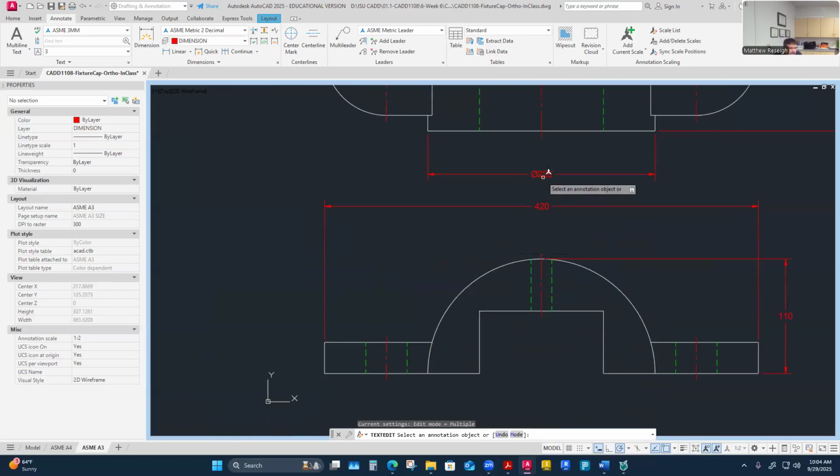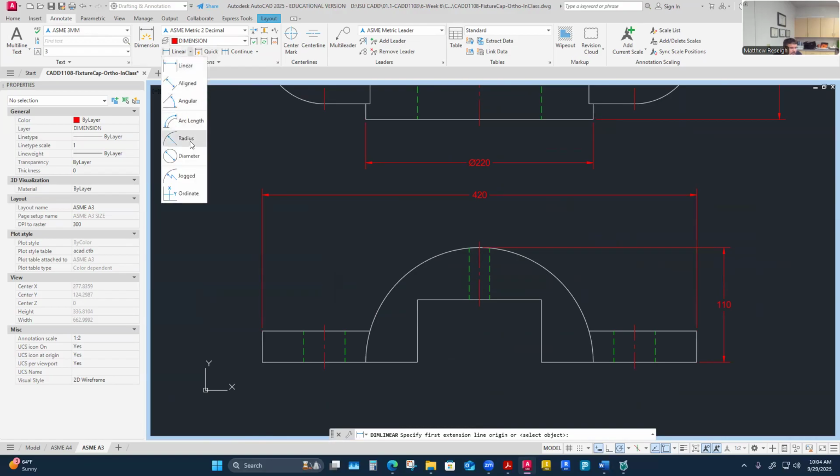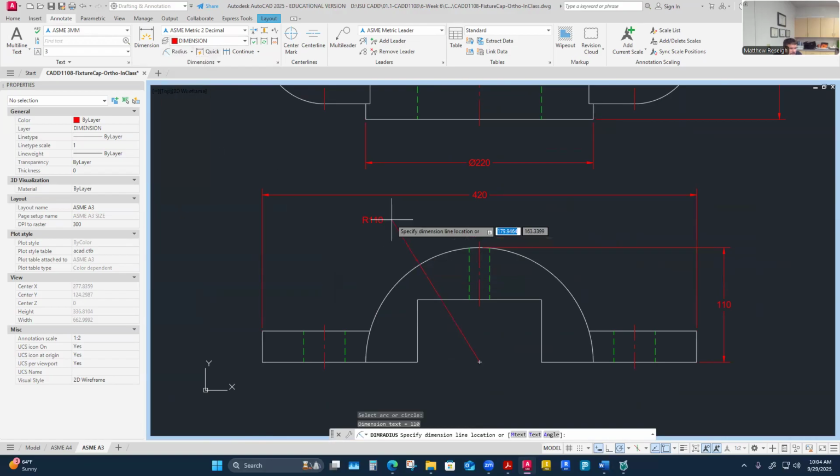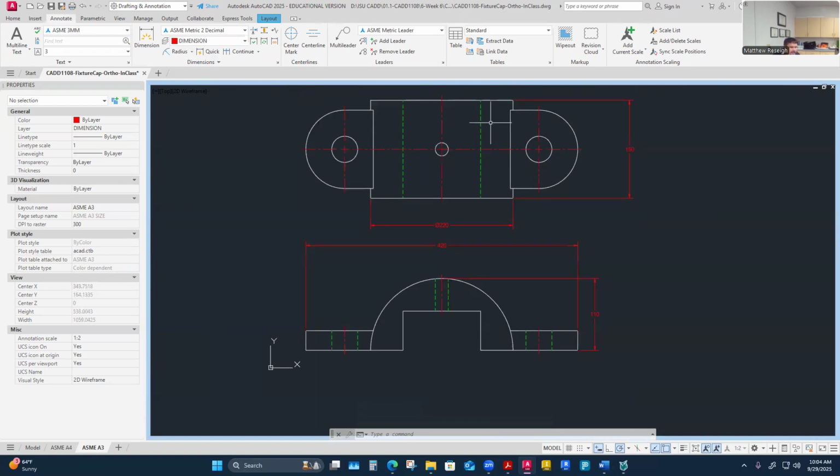That's a better practice than the good practice of just pointing out a radius here with a leader type dimension, which I'm not going to do because it would be a redundant dimension. That wouldn't be wrong. Maybe it's just a good dimension. This is a better dimension. So that really accounts for that part's